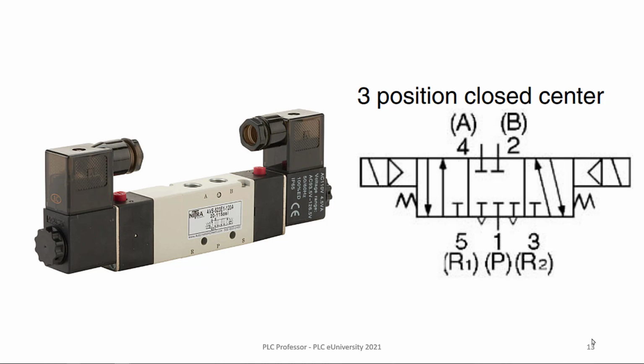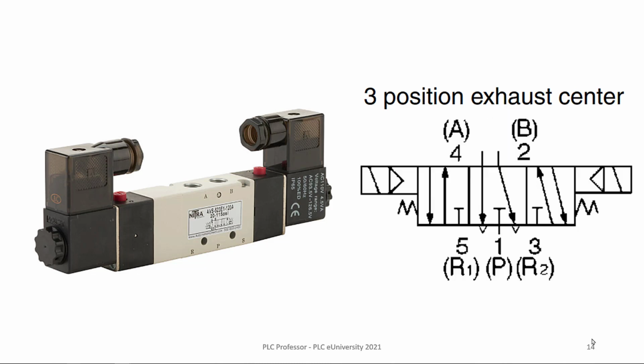Which means that the cylinder has that pressure trapped on one side and it more or less keeps it from moving. So 3-position closed center. Remember, I'm telling you more than you need to know for this virtual machine, but why not?